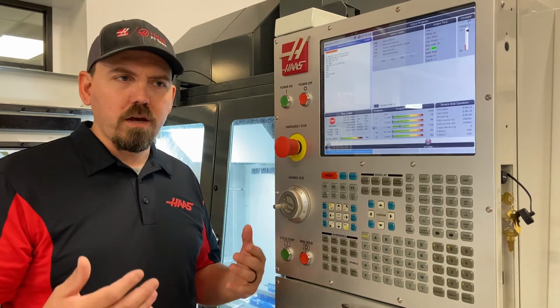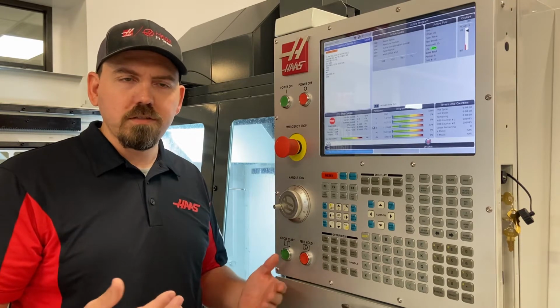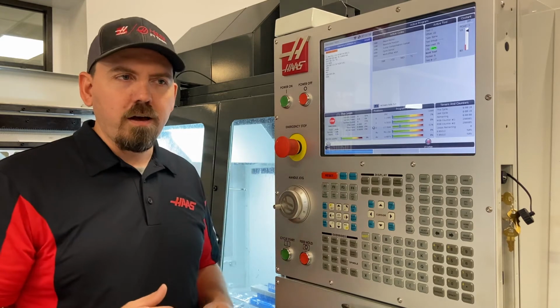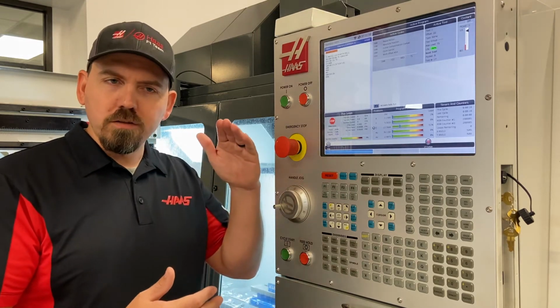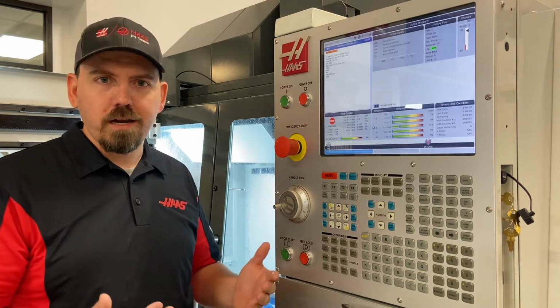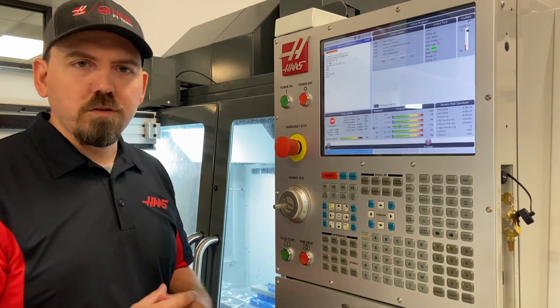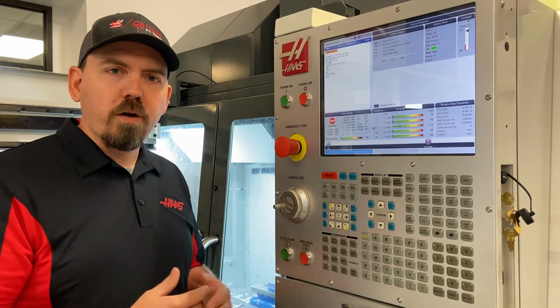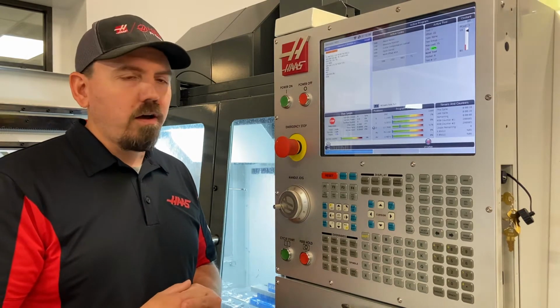But people with the probe system, the whips, you tend to have a positive actual tool length, and having a zero value can cause the spindle to try to machine your part. Not a good thing, cause a crash. So today's video is to prevent that. What can we do to work around and prevent that from happening?